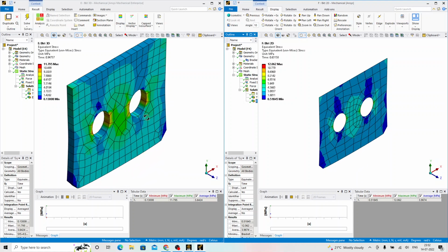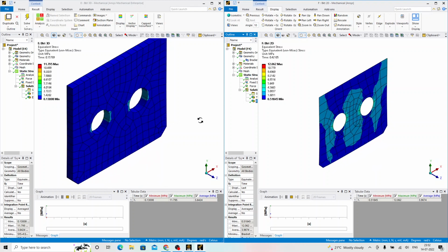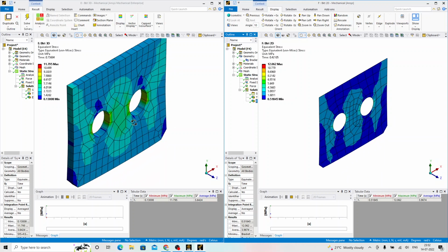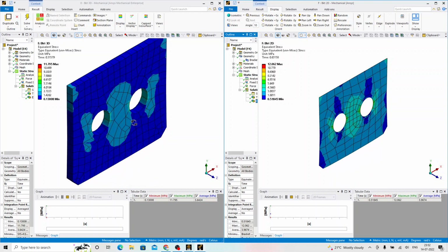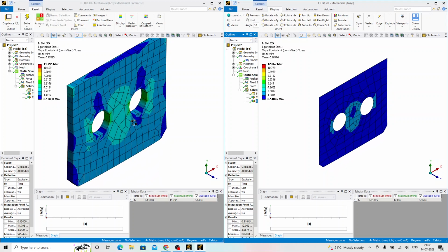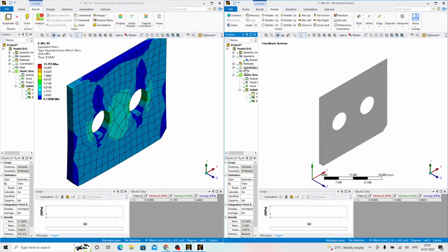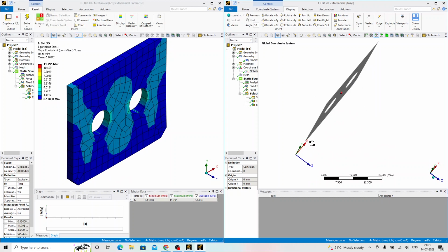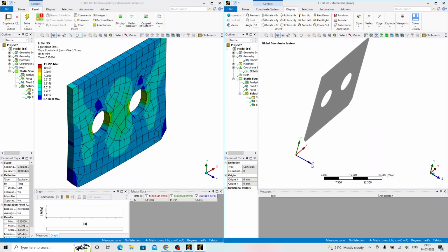In both the cases, computation time for 3D is higher, computation time for 2D is lower, but the results are almost the same. Whenever you solve such problems wherein the geometry is planar and there is only in-plane loading happening, and the expectation is that deformation is also going to happen in plane, then immediately that geometry should be treated as a plane stress analysis. The condition we must remember in this case is the geometry should be lying in the xy plane only, and not even a single micron of offset in the z direction is accepted.